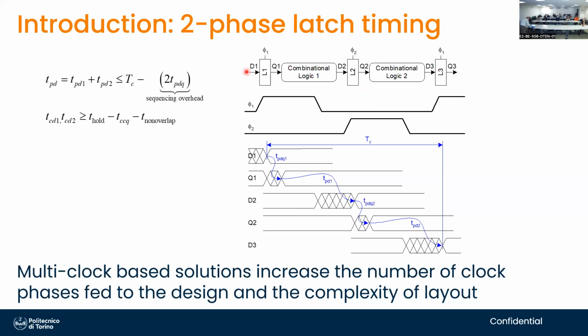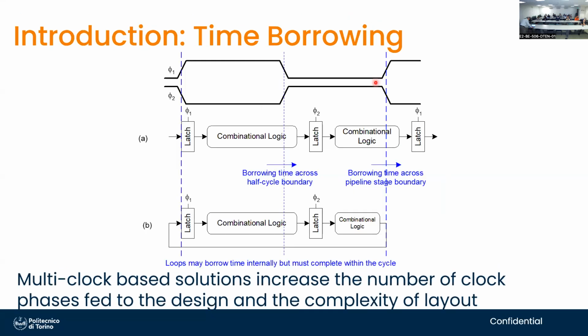Latch-based design will have an open latch here, an open door here for some time. There will be another open door here for some other time. They will never be open at the same time, otherwise people could just race through. But they can do time borrowing. So if they get here early, they can go through and start doing work on the other side, or vice versa, as I was mentioning. And this is called time borrowing.